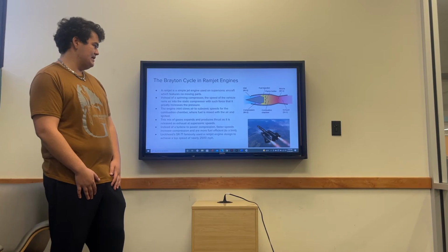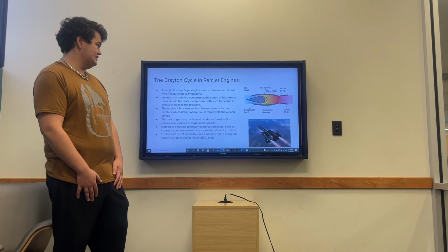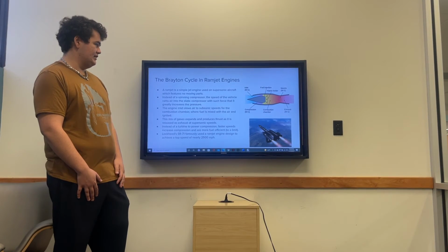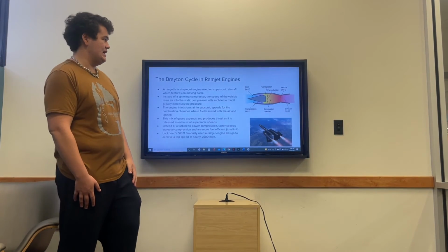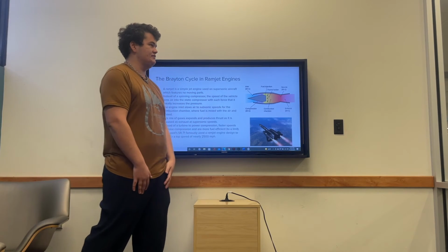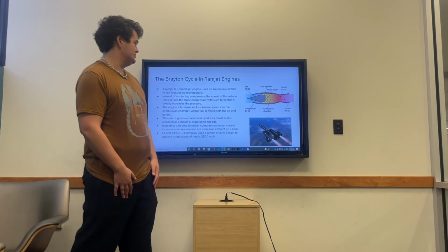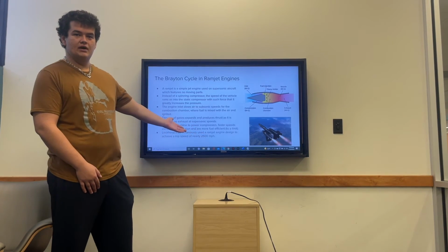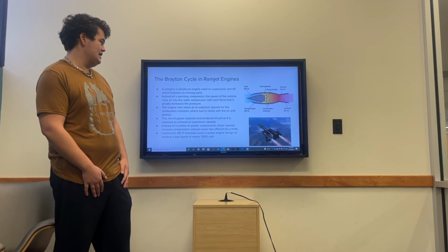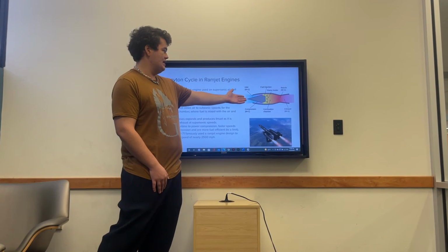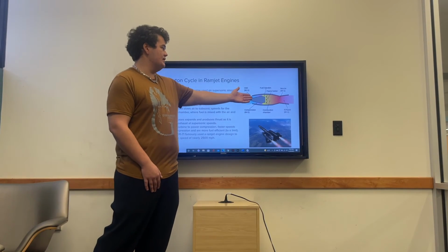Instead of a turbine to power compression, as in the last jet engine, faster speeds are going to make the whole flight a cycle, and faster speeds will actually make it more efficient as it's going to create more compression at the front of the engine, to a point with aerodynamic inefficiencies. This is going to create a max speed of about 2,500 miles an hour for the SR-71, and again, that depends on aerodynamic inefficiencies at the inlet of the engine because you need subsonic combustion.